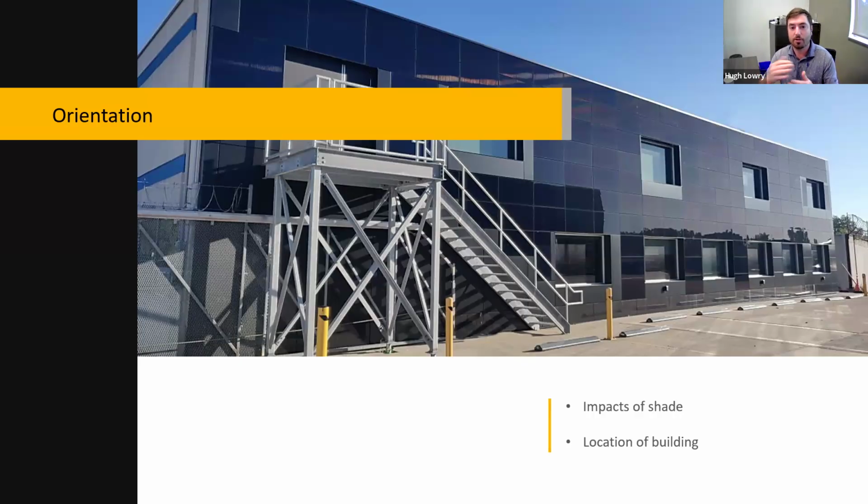You can have things like sunshades, and making the sill panel for windows a solar panel, that can help direct the panel back more towards an ideal angle. But typically we are stuck to a 90-degree tilt perpendicular from the ground, and we don't generally see motorized or articulating systems involved in BIPV as well. So they tend to be fixed or stationary.